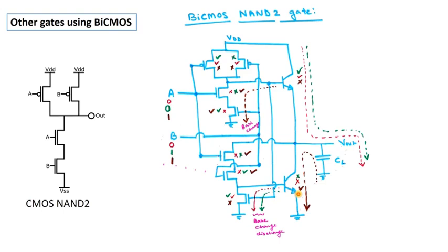Okay. You know, in the last slide we discussed that there should also be a path for base charge removal, or a reverse base current path. So, we have to provide that. One NMOS transistor has been used here, which can remove the charge of this bipolar junction transistor, as shown here. Whereas, for this case we need two NMOS transistors, as shown here.